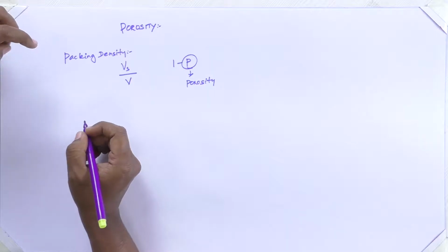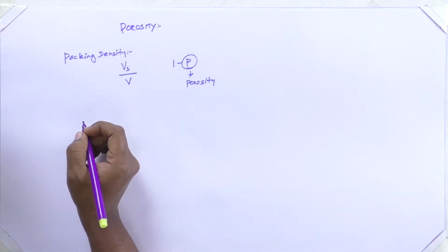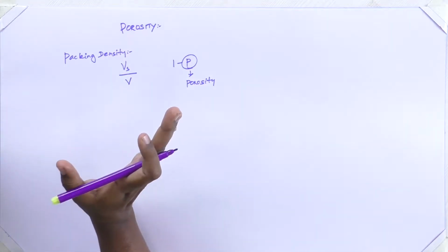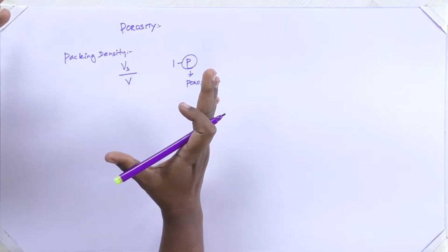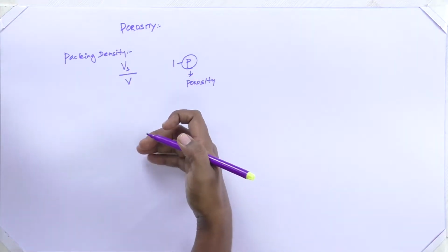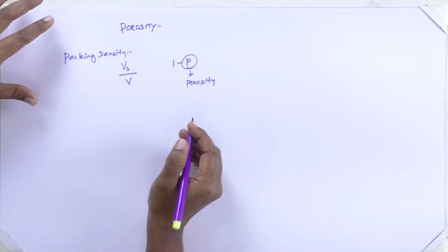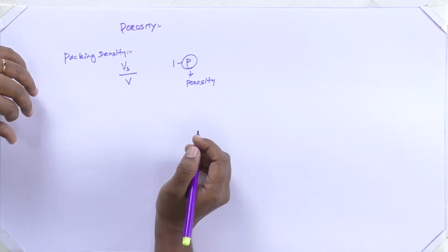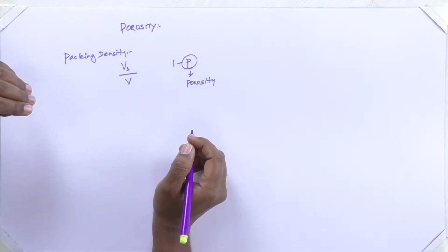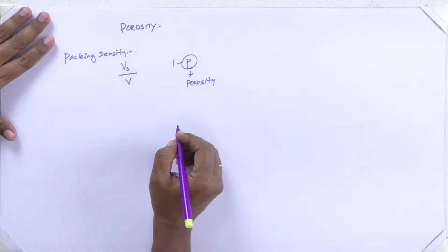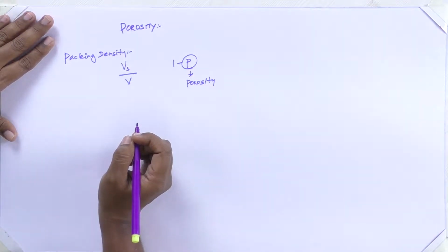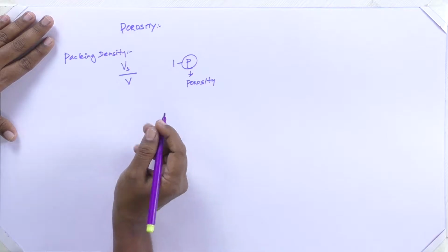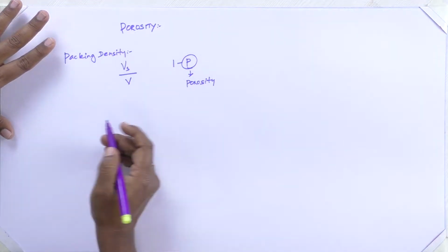Packing density of single sized aggregates. Now let's discuss single sized aggregates alone. When these single sized aggregates are packed together, how will their packing density be? Let's see through an example. For simple cubic packing, the relative porosity is around 48%. Let's see how that simple cubic packing will be.